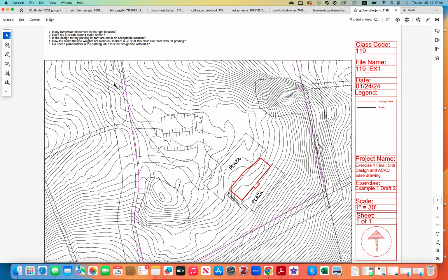Turnaround makes sense. Well, it shouldn't be connected to the parking lot. You don't want people to be confused once they drive around here and then need to decide if they go into the parking lot or return back. You would want it to be simplified. The buses go over here and then just drive out of the area. Do not encourage buses to go over here. And when you have such a limited area, this intersection is going to be pretty chaotic.